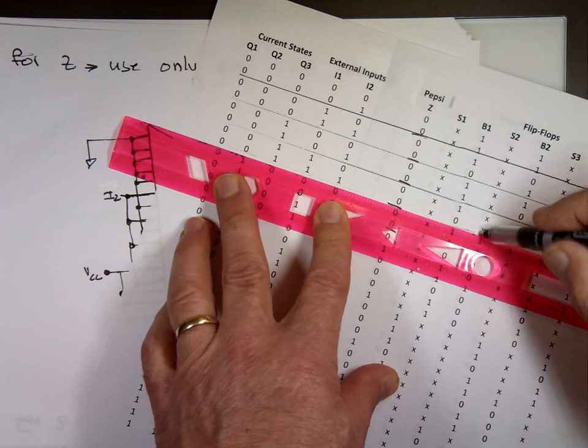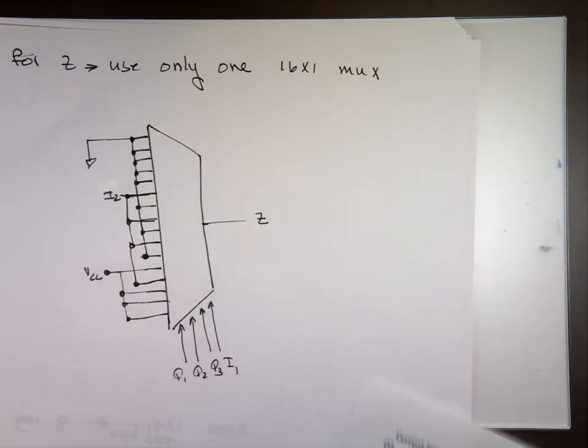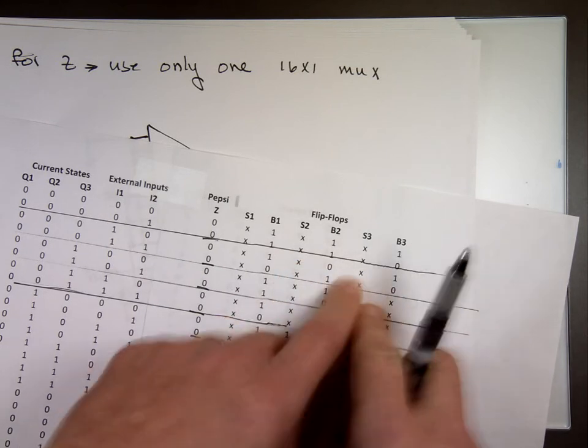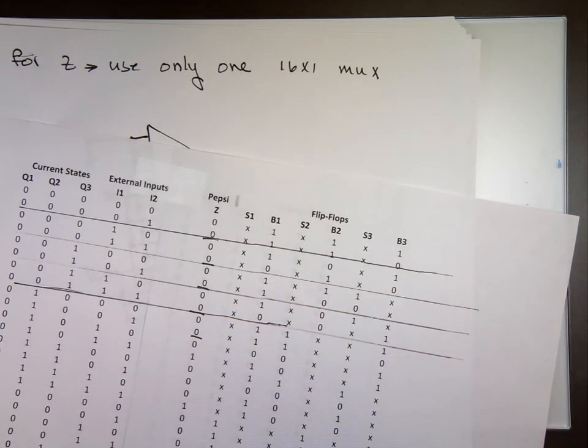And now we can go and design the rest of them. We need to design one for S2. We did that. This one, that's ready to go connected. Now we have two more, S2, B2, S3, B3. We can decide what we're going to use. Do you use two muxes? I can use muxes, I can use ROM, I can use PLA, I can use PAL. So I probably like muxes. Well, muxes will make it actually nice and clean. That's what they do. You can use gates, whatever. It's really preference for the design. I'll let you have fun with it.